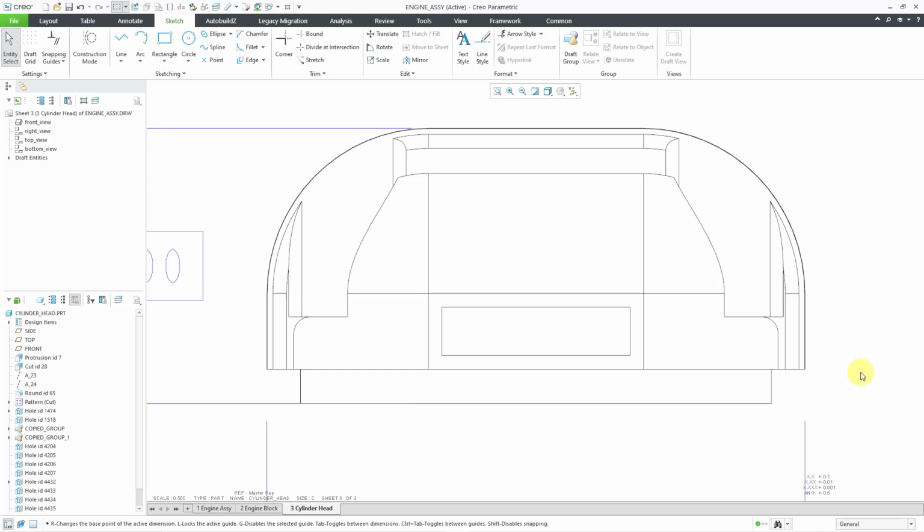What I mean by that is sometimes people need to add a hole into the model and they say, oh, you know what? Rather than going back to the model and creating a hole feature, if I just sketch a circle right on here, well, it's going to look like a hole. This is a very bad practice. So I'm going to select that circle and then delete it from the mini toolbar.